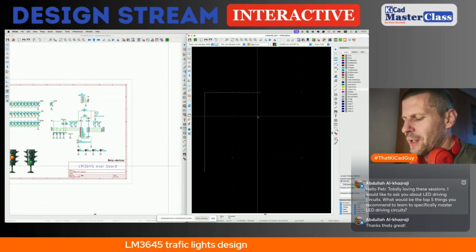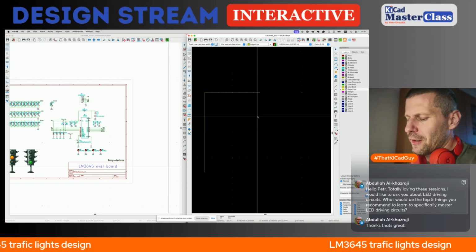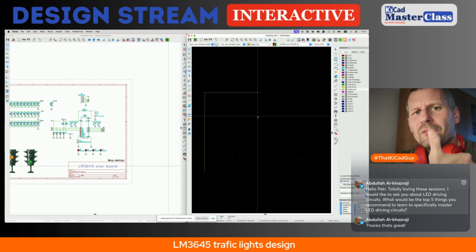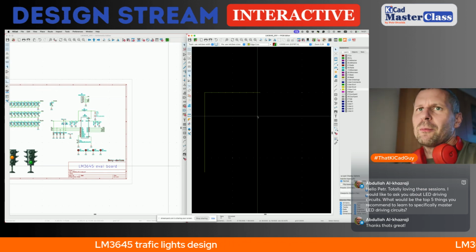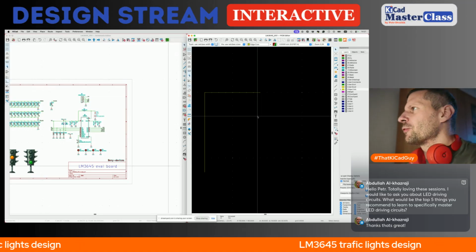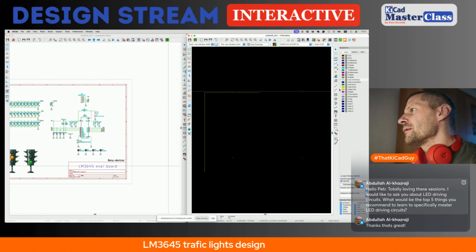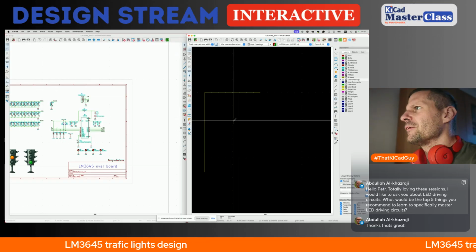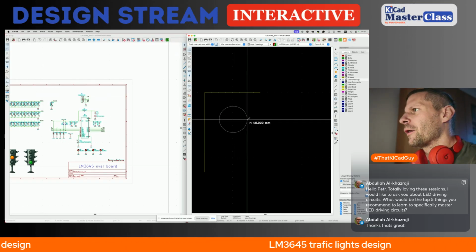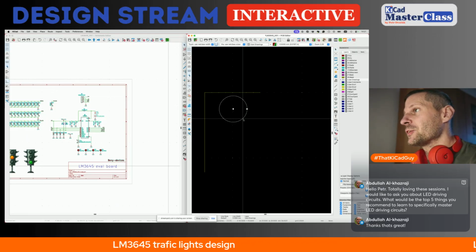I don't know, we have 11 LEDs of 3 millimeter. I think a thumbnail size of the light can be fine, which is about 20 millimeters. So a circle in diameter of 20 millimeters can be used. It means that we have to start with the circles because they will drive the shape of our PCB and as well the size of the PCB.